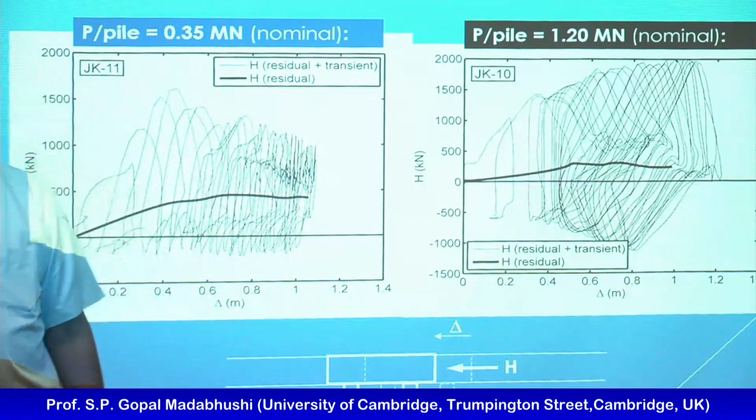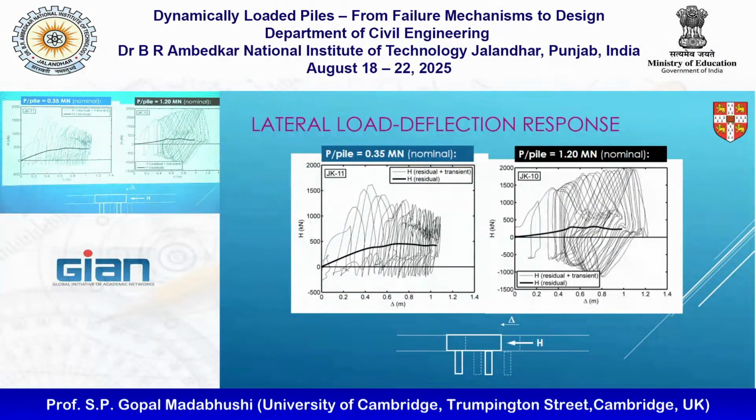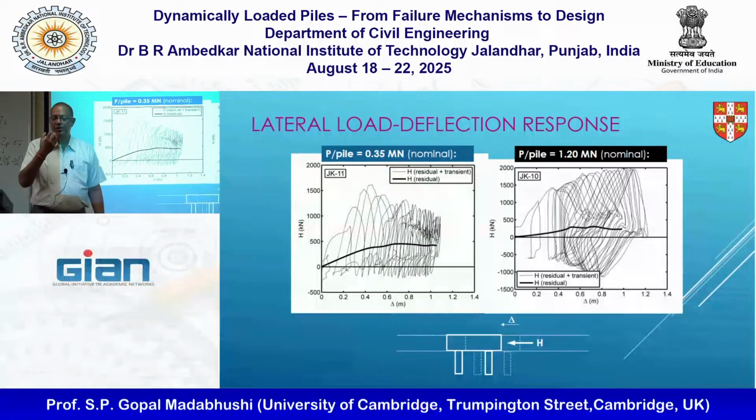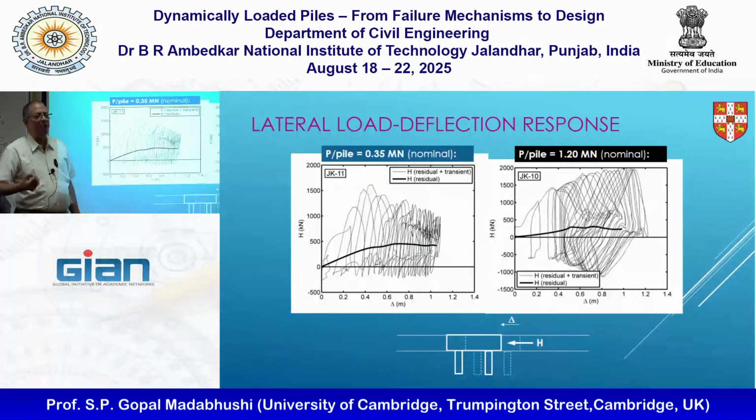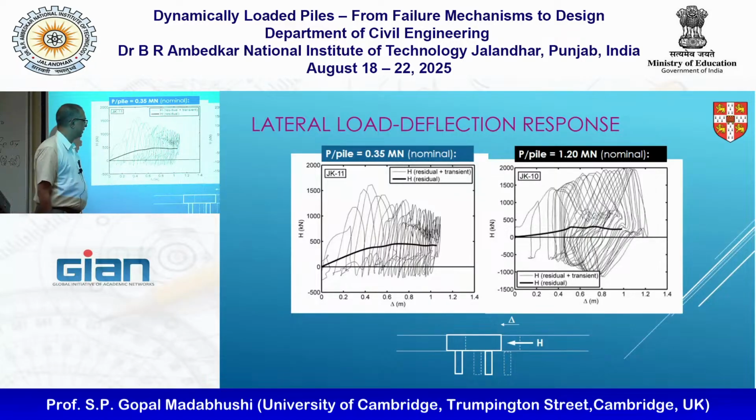Because the amount of force that the clay layer can apply is relatively small compared to the axial load the pile is carrying. So whether the slope wants to go down or not, it still has to cope with the axial load. So that will oscillate because it has the inertia both positive and negative side that is driving the piles. Okay? Right. So this is experimental evidence.